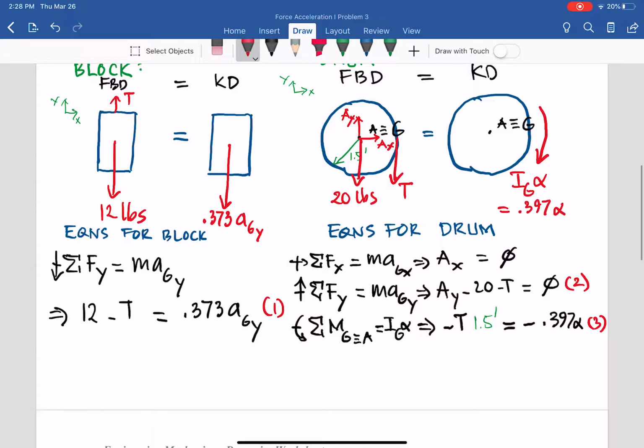Take a look, listen. So you have 3 meaningful equations. Let's count how many unknowns. Don't solve until you have enough equations to solve. That is the bottom line. So let's count it. T, 1 unknown. Ay and Ty, 2 unknowns. Fx, Ax, you already solved, so we don't need to count that. Ay, so it will be 3.